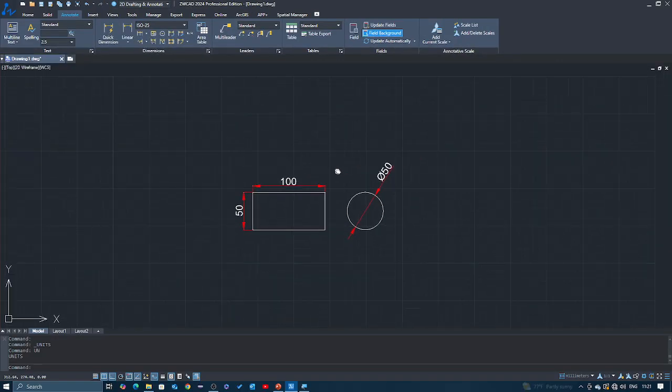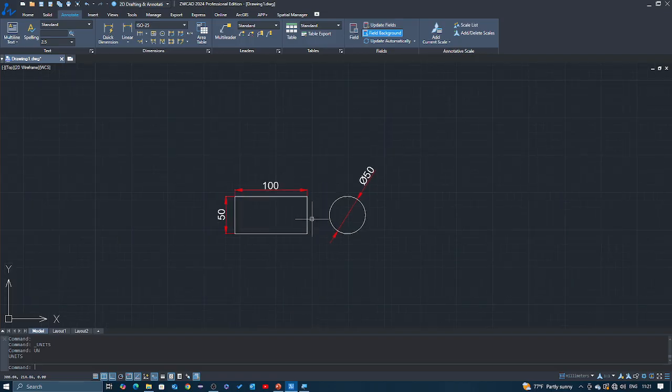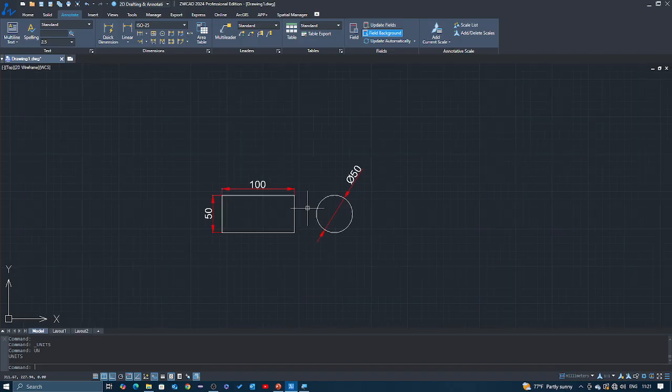So what is the importance of unit of measurement, or unit setting? Sometimes if you don't show the unit of measurements, then for the next process, whenever you want to release the drawing for manufacturing purposes, you will get a lot of issues with the drawings. Somebody will be reading it and think it is a centimeter, no, it is a millimeter. So along with that you have to mention these drawings are made in millimeters. Read all the dimensions in millimeters, unit settings.